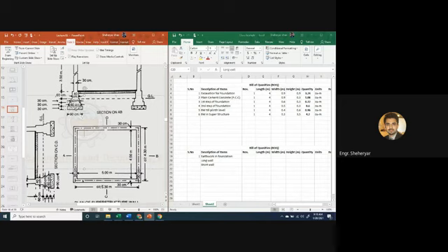Actually this will not be exactly 90 centimeter, but here we take 90 centimeter, because if you excavate the ground with exactly the same width as that of the PCC, it will be difficult for the labor to work in the excavated portion. So you will have to provide some extra margin for the laborers to easily work there. But for this example, we'll just take it as 90 centimeter width.